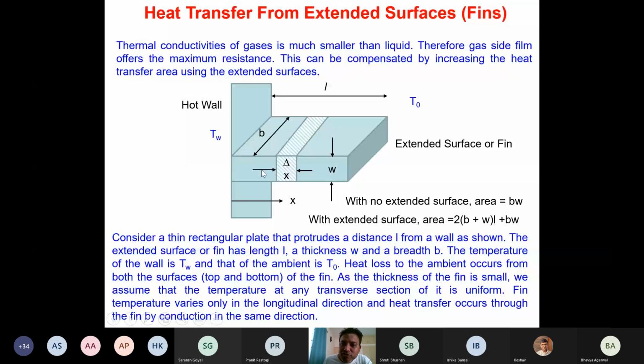So what is the assumption? Remember, we are moving along this x direction. The amount of heat that is being conducted reduces as we move along the x direction, because we keep on dissipating the heat from the top surface, bottom surface, or the side surface. So by the time I reach this particular end, which is x equals L, all the heat that is being conducted is already exhausted by convection. So at this location, minus k dT by dx equals 0. That is what the assumption is, and it's a realistic assumption.